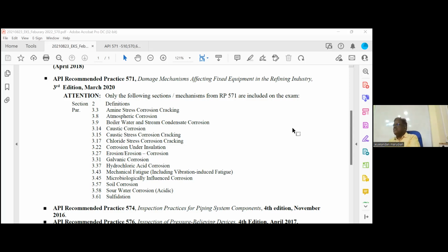In the external inspection, they will check support condition, foundation condition, painting condition, the insulation condition, whether the pipe is vibrating, leaking, or misaligned. All this we can check in the external inspection. We can use some mechanical tools, but we will not use NDT. The third one is on-stream. On-stream means checking the inside condition from the outside. How will we check the inside condition from the outside? By NDT. The generally preferred NDT methods for on-stream inspection are RT and UT. For some particular diameters we can use RT also.